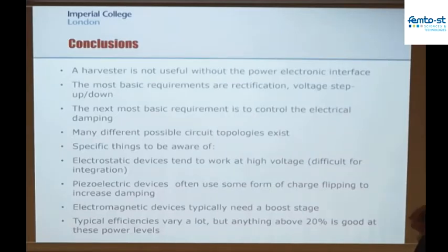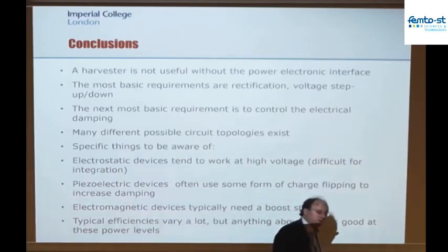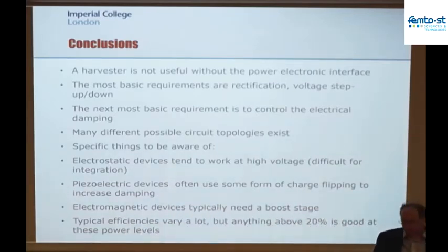So just to conclude then, the harvester as a unit, just the piezoelectric material or the electromagnetic transducer or whatever type of harvester you're building, is not useful in isolation. It's got to have the electronics attached to it to make it useful. And at a very basic principle, that means taking the AC and converting it into DC so you can power some load electronics. And if you can't do that, then the harvester is not useful to you in a system. In reality, then, what we can do is to start thinking about that electronics as not only something which is doing the basic AC to DC conversion requirement, we can think about it as something now that can really help to optimize the system.